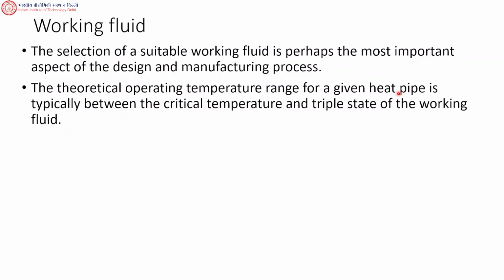Right, so working fluid is one of the factors in there. So what working fluid do you choose? It will depend on the temperature at which it has to operate, how much heat it has to transfer, and things like that. So the typical operating temperature range is between the critical temperature and the triple state temperature of the working fluid.